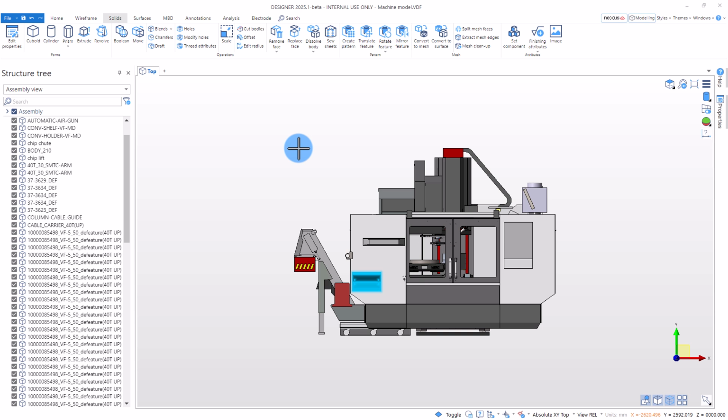another thing to show is that if you right click, you can see this area over here, which you drop down, has the latest commands which you have used, and usually these would be the reduce command, remove face, and replace face. And if you're using the top view, just as me, to be easier to have a look at your part, this one will be there as well.